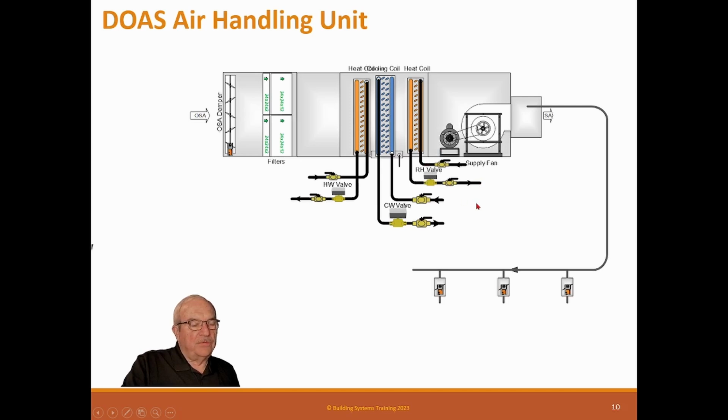And the reason for this is we want to put all the complexity up here in one unit instead of having all that complexity down at each unit. Plus, we want to be able to maintain the outside air filtration all in one location. So these are used to make it simpler and to provide a better environment. Now, they're designed to trim off the outside air. They're not designed to provide cooling to the unit. They're designed to actually feed this at return air temperature.